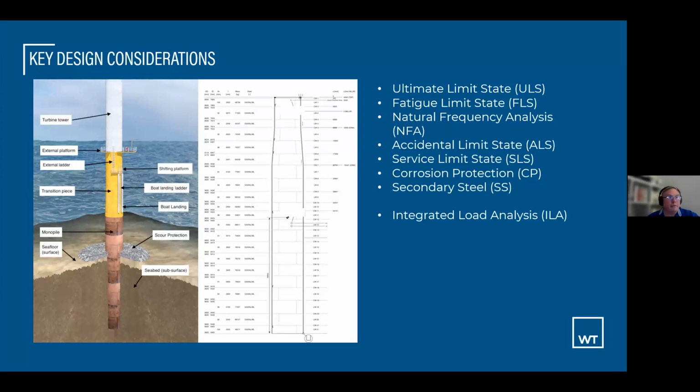So we have to analyze diameter and length against the natural frequency of the overall structure, and make sure that we're not getting into any natural frequency resonance. If that isn't done right, then the entire structure will resonate. You may have seen the famous bridge that was doing this when it hit its natural frequency. That's, in engineering terms, a bad thing. So we have to avoid that and analyze the natural frequency.